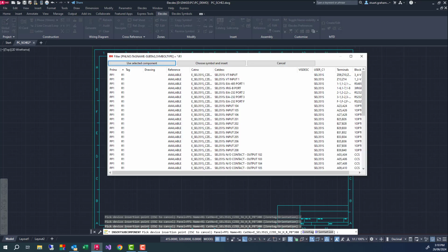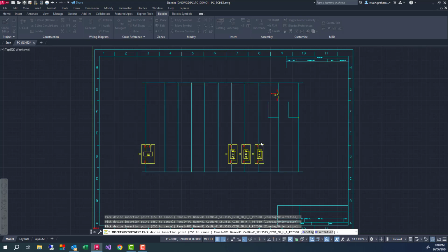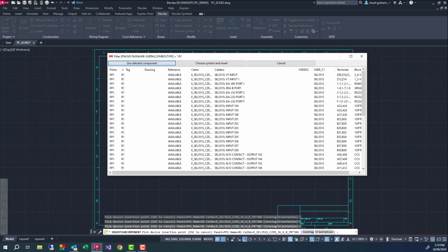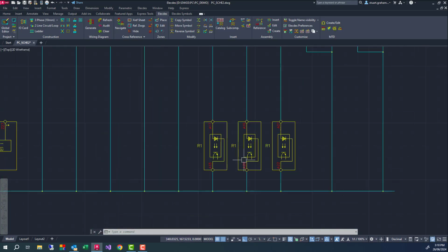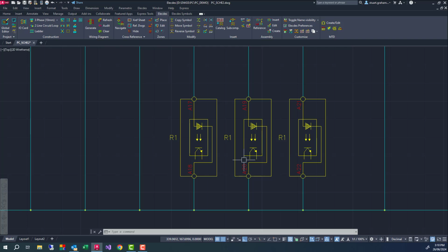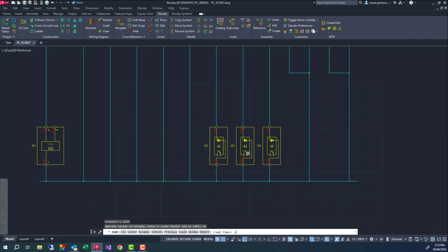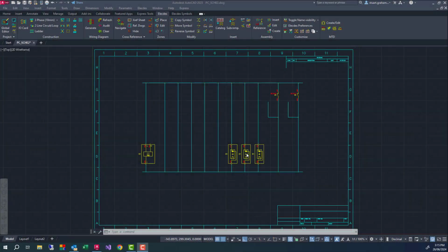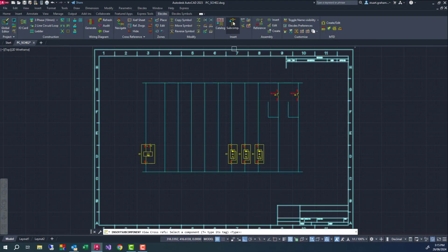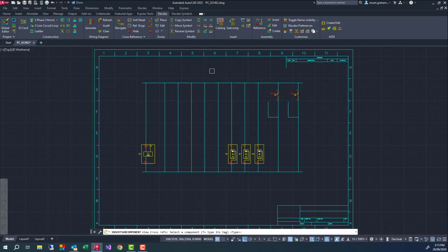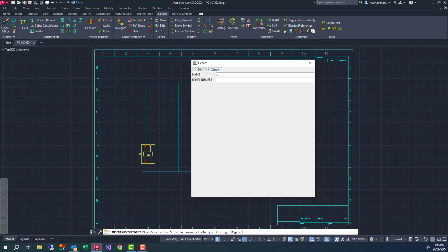These subcomponents use simple contact symbols. All attributes are loaded automatically from the relay's catalog specification. The CB1 breaker has 3 alarm contact outputs and 2 trip coils that I need to integrate into my protection circuit. These will go on rungs 2 to 6. I'll insert the contacts first. Again, management of the contacts is very important in this design.